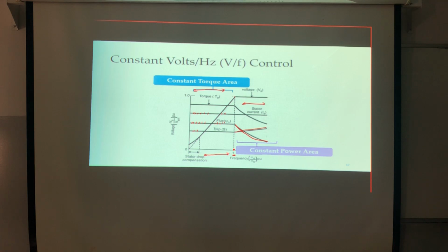And there's F max. F max is either related to the omega max mechanical or to the inverter maximum frequency. Now, in general, I need an inverter in order to control the amplitude and the frequency of the AC signal, correct?